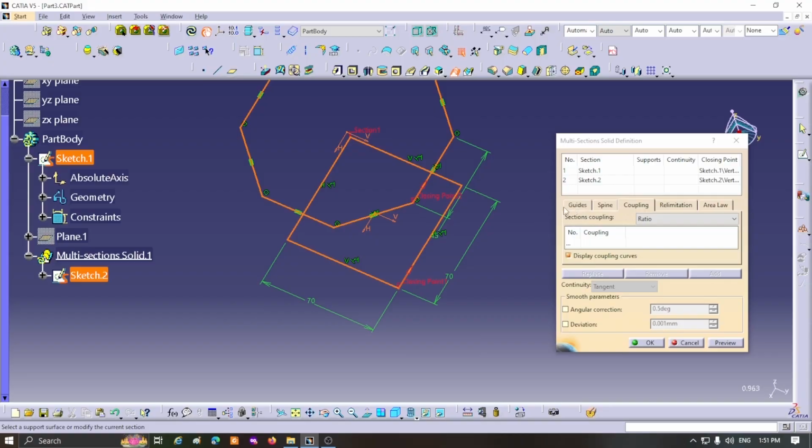In the second part of the definition window, I'll click on the coupling tab. The coupling window opens. In the coupling window, we specify which points should correspond to each other. To do this, I'll click on the 3 dots inside the coupling box. A blue row is created in it.